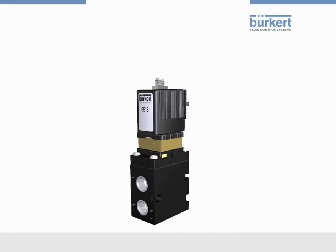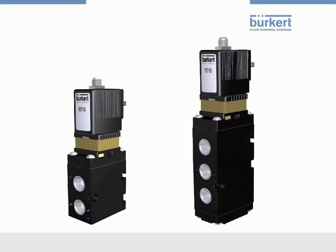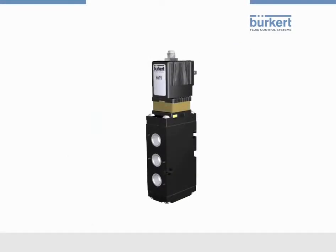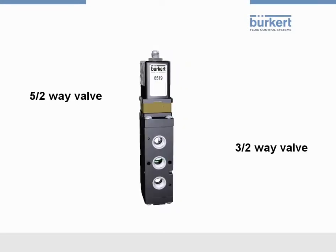Type 6518 is, together with Type 6519, one model range. Type 6519 is the more universal valve and offers more functions. That's why we take a closer look at this type. We have the possibility to use the valve as 5-2 or as 3-2-way version.